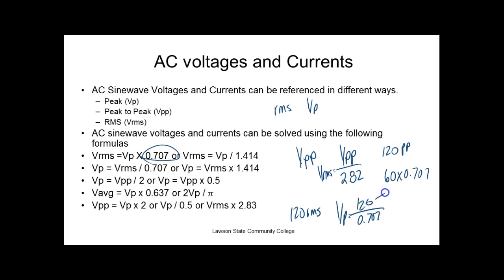By the way, what voltage do you have at your house? Well, we have all types of voltages, you know. So what does the National Electrical Code say? They have what they call the nominal voltage. So they use 120 volts. So we use 120 volts a lot, even though odds are it could be anything. It could actually be plus or minus 10%. So you could have 90 volts at your house and it would still be legal, right? You understand that? Normally your voltage is anywhere between maybe 110, 109 up to maybe 120, 120 something volts.